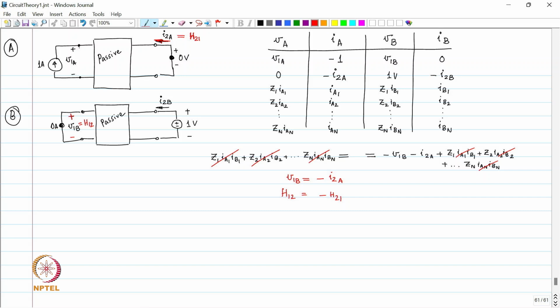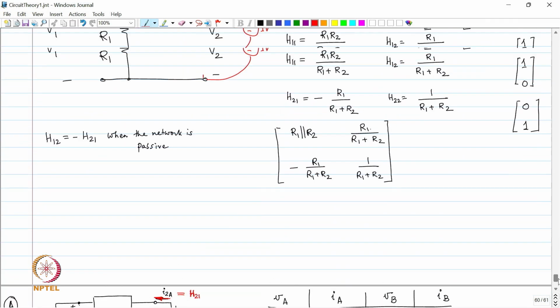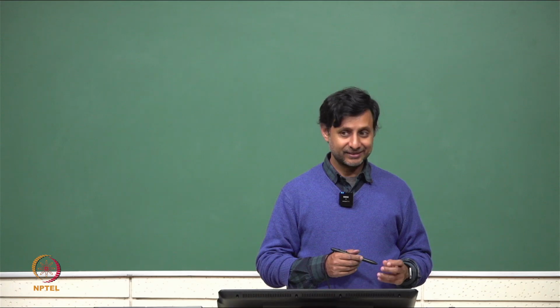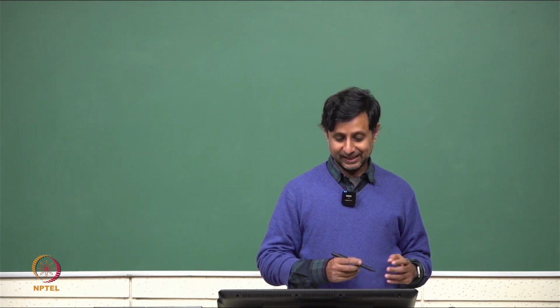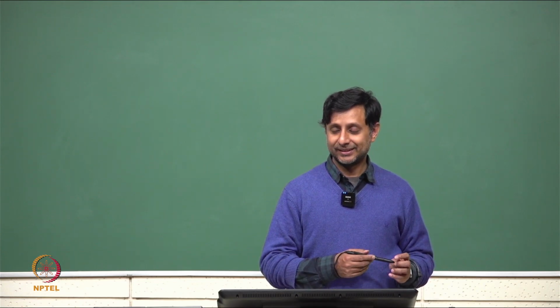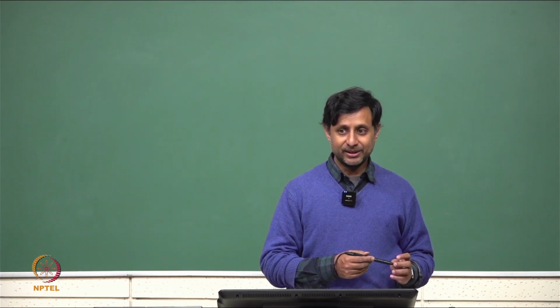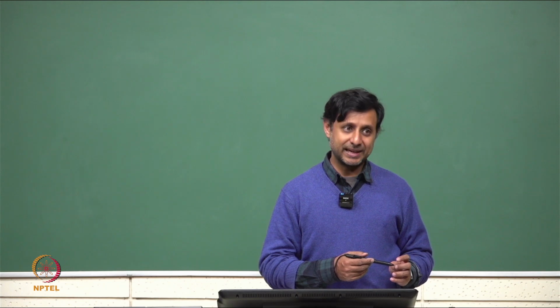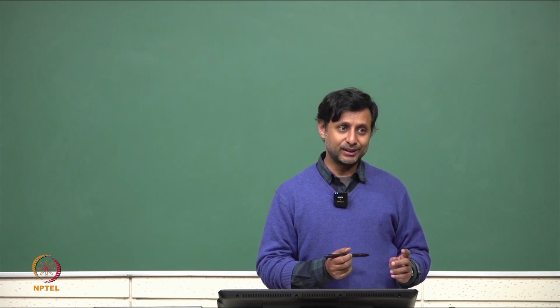Fine. All right. Could it be minus R? Could there be a minus R inside this? Would it still follow Ohm's law? Would it still be okay? Can I have minus 1 ohm inside the network? It is giving power, but it is still following Ohm's law. It is not a passive network, agreed, but it is still following Ohm's law.